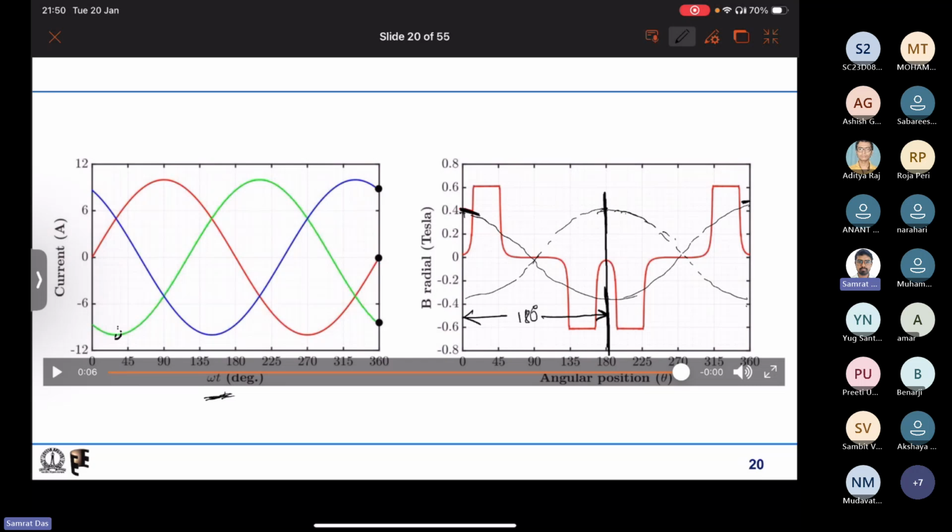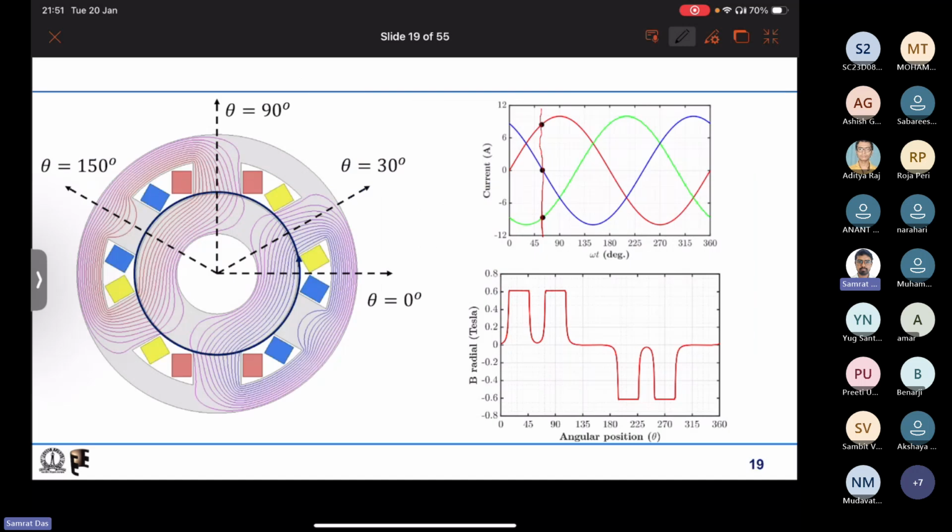So, because you have taken electrical in the basic course, right, what do we actually mean by the term synchronous speed? You know the formula for that, right? 120 f by P, that is the rotations per minute. What is this actually? For f equal to 50 hertz, and if we have two poles as we have in this case, what do we mean by two poles?